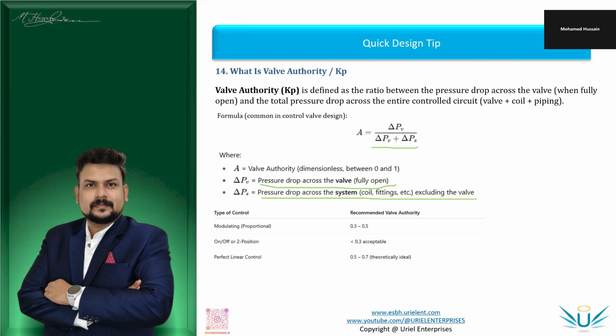That's the summation. Here we have the pressure drop already. It is known as 3.85. And then what is the summation of the pressure system? You have to identify the system pressure. How can I identify the system pressure? You can get it from the head pressure, from the pump equipment cut sheet, or from the chiller side head pressure near whichever pump they are placing.